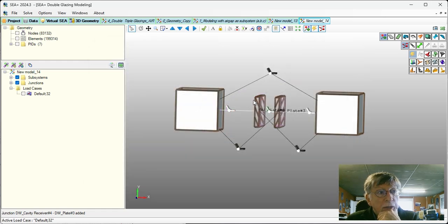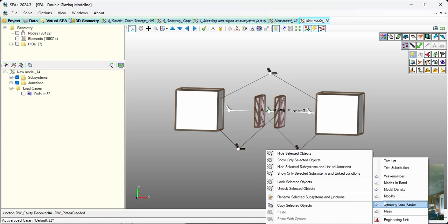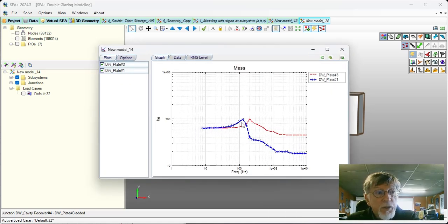simply supported. What you see is that when you couple the mass of the plate by the transfer matrix approach, you have an increase of mass. At low frequency, you have one mass, the mass of the total assembly. Everything is moving in phase. So there is only one large subsystem at low frequency around the first mode, and the fluid acts as a spring between the two panels. So you have at some frequency, a breathing frequency in this region.